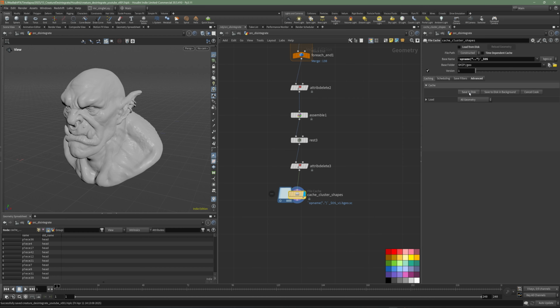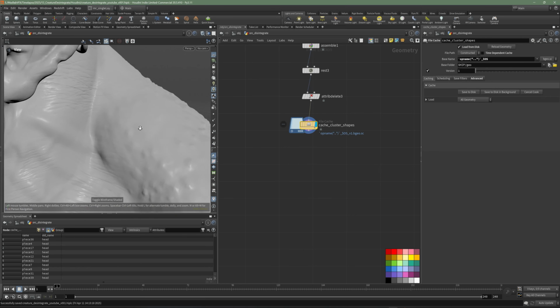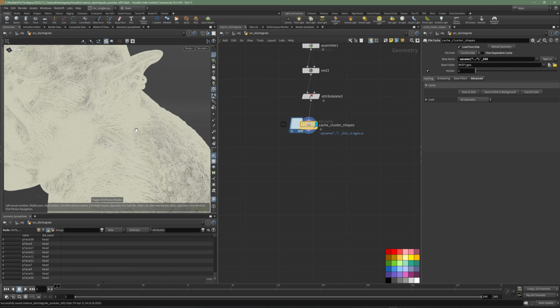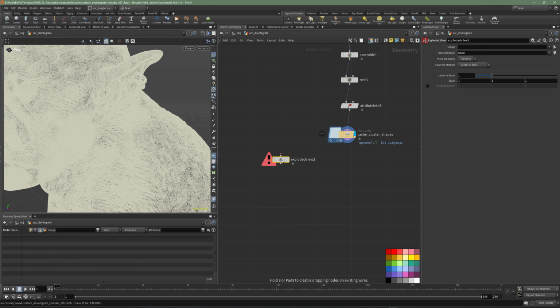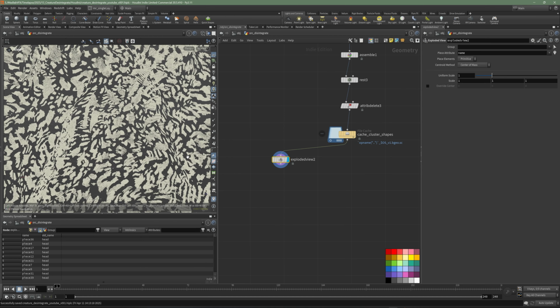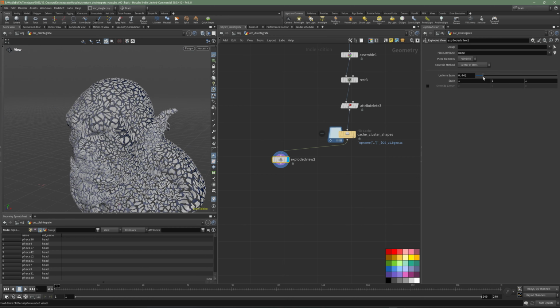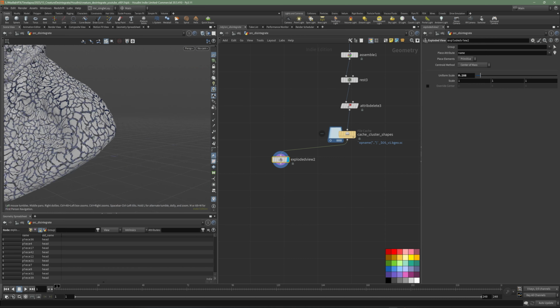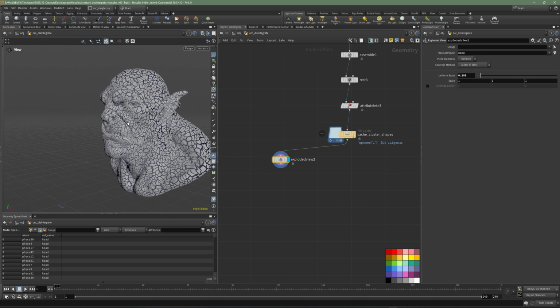Let's save the cache. Right now, we can see here the geometry is too dense, but we don't have yet the separation of this piece. Let's use the explode view to check if the fragments are working. Perfect. All the fragments are working. You can see here the separation. This technique of fragments using cluster is very good instead of using the legacy Voronoi technique.